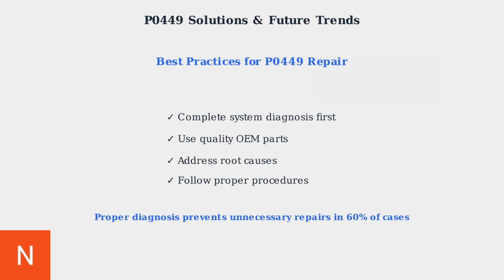Proper diagnosis prevents unnecessary repairs in 60% of cases. Remember, successful P0449 repair depends on thorough diagnosis and quality parts. While the vent solenoid is the most common culprit, proper testing ensures you fix the actual problem the first time.